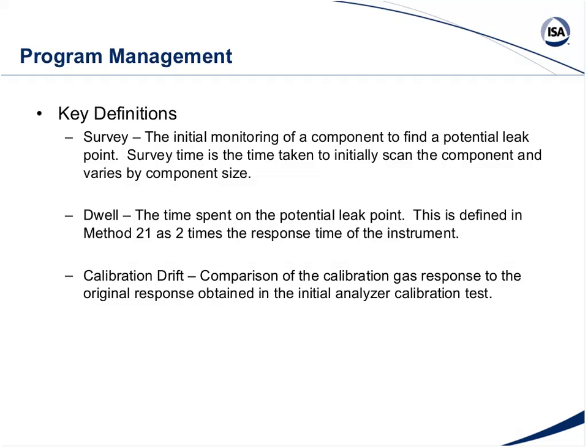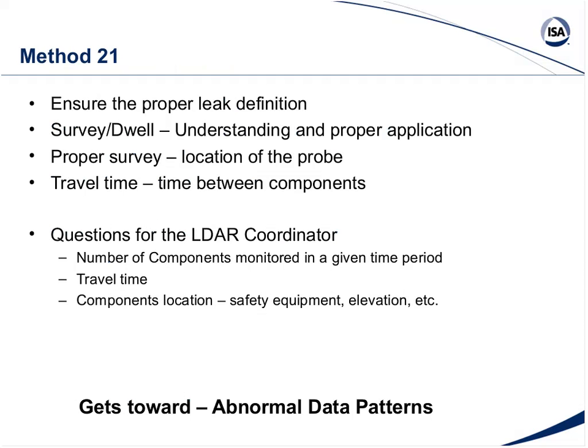And the third time element that you want to keep in mind and consider is travel time between component to component. When I'm doing database forensics, I want to look at my survey time, my dwell time, and my travel time. Is that reasonable for the monitoring route that's being run? And we'll talk about that here in just a second. So I want to look at my proper leak definition. I want to make sure I'm doing a proper survey and a proper dwell, a proper survey in where the probe is by component type, and I'm looking at that travel time between components.